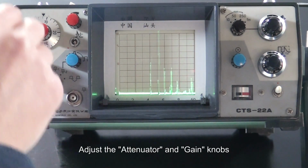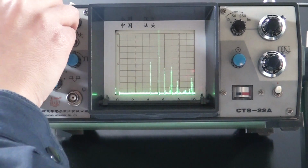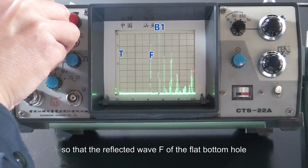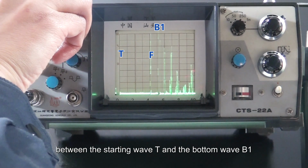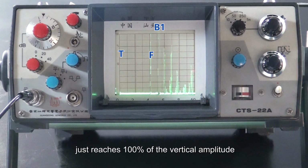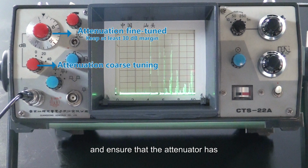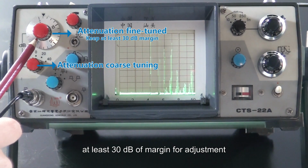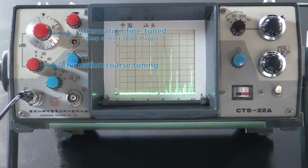Adjust the attenuator and gain knobs so that the reflected wave F of the flat bottom hole between the initial wave T and the bottom wave B1 just reaches 100% of the vertical amplitude, and ensure that the attenuator has at least 30 dB of margin for adjustment.